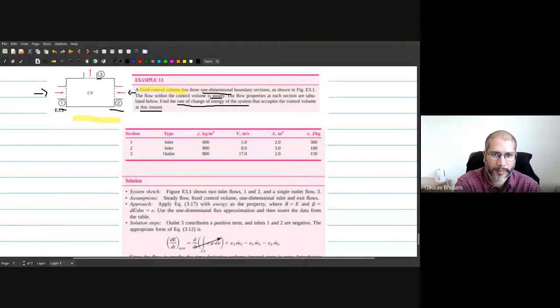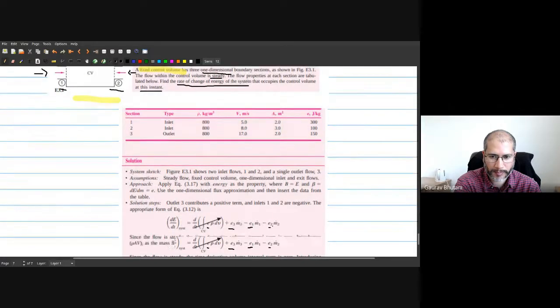of the system. Remember, we talked about that Reynolds transport theorem can be written for any extensive property. So capital B is also an extensive, capital E, that is energy, is also an extensive property. And the corresponding intensive property then becomes energy per unit mass, which is written using this small e symbol. Okay. So this dE by dt for the system is the dB by dt for the system in the Reynolds transport theorem.